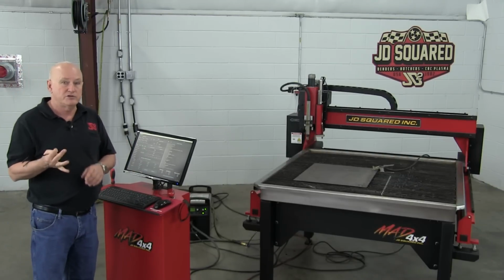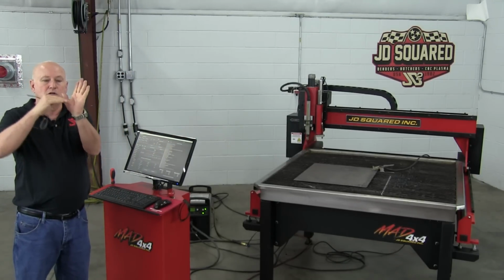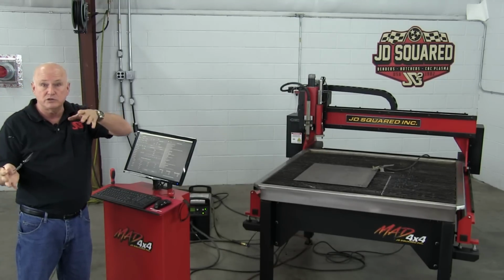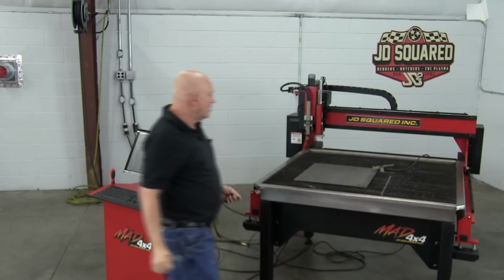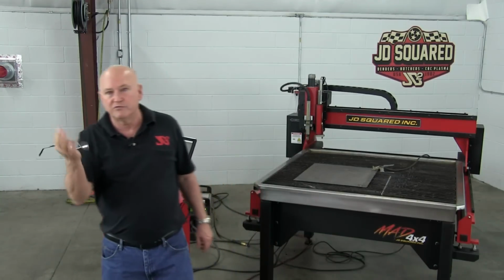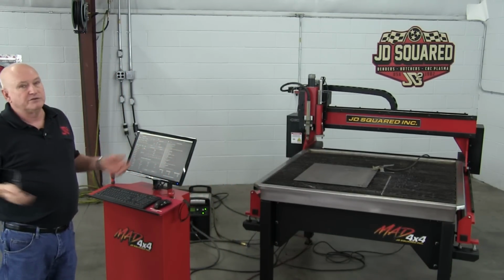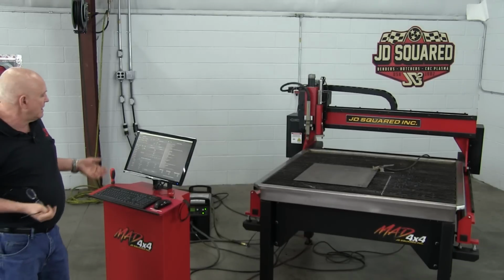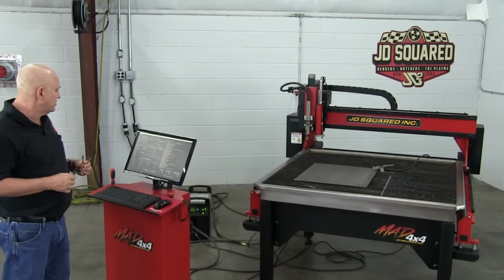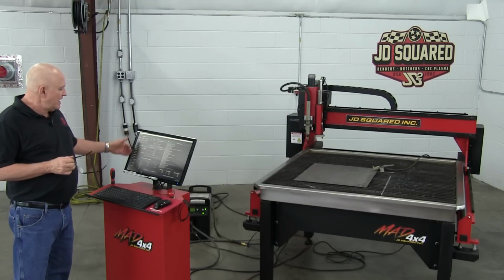What's the difference between shielded and unshielded? Shielded is your shield on the outside. A shielded consumable is not going to allow the tip to physically hit your metal. It's going to be just below it. It's going to shield it, you know. Why? Well, you've got an ohmic machine. You're touching off. You don't really want to be dragging your nice, pretty little orifice in your tip on this metal. So the shielded one protects it. I myself have never cut with unshielded, but Hypertherm does list all these different ones, so we have them built into the tables. In the real world, just use shielded and don't worry about the others. But anyway, we have these different settings.